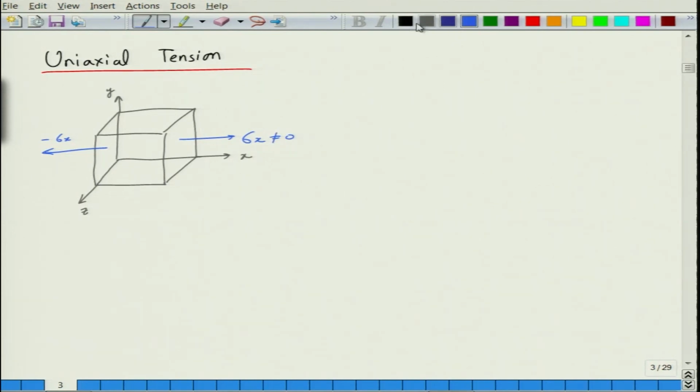Okay. So, we say that sigma ij can be written as sigma 1 in terms of principal stresses, 0 0, 0 0 0 0. So, only one component is finite. This is the uniaxial tensile stress that we apply to the sample under uniaxial testing.